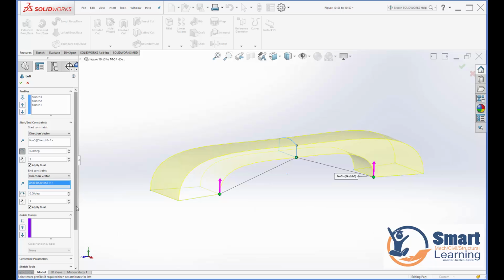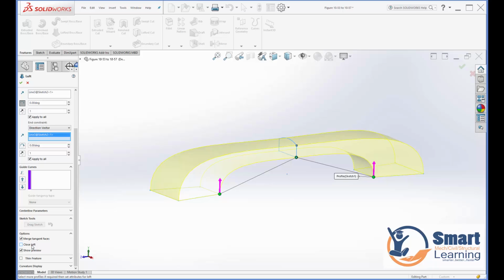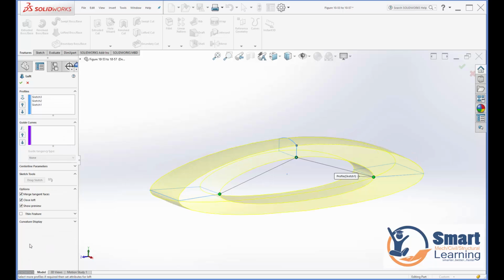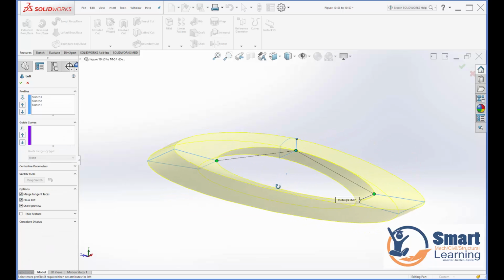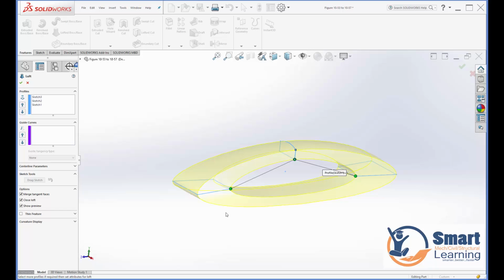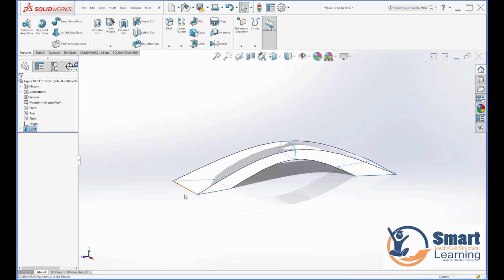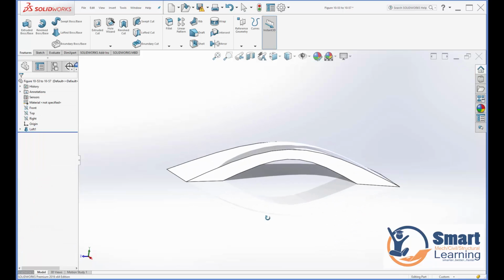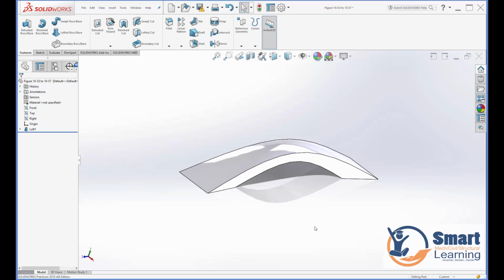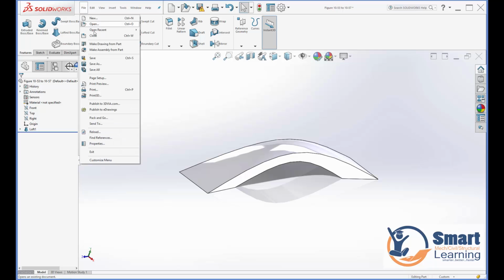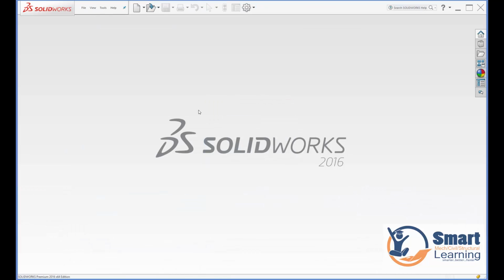And also, if you look at this closed loft which I was discussing before, that you cannot apply in infinite parallel sketch, but here you can. And like this, you can end up with this another bottom part where you can have another loop as well. And finally, you can finalize this. So these are the options which will be handy for creating complex objects with contours.